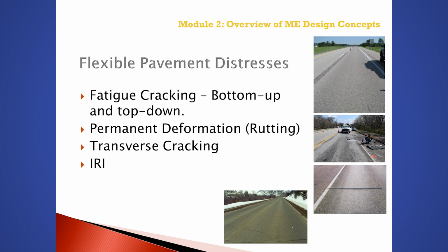Transverse cracks occur perpendicular to the pavement centerline and are a result of low temperature events, thermal cycling, and/or shrinkage of the asphalt mixture. Transverse cracks are measured in length and recorded as total feet per mile.